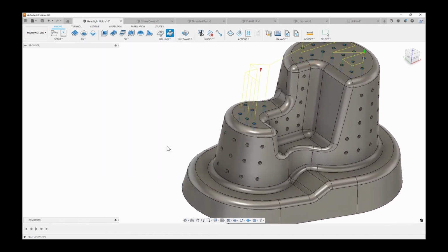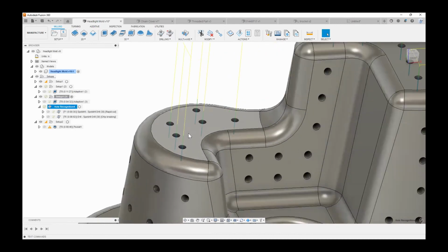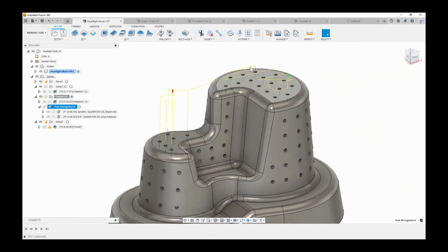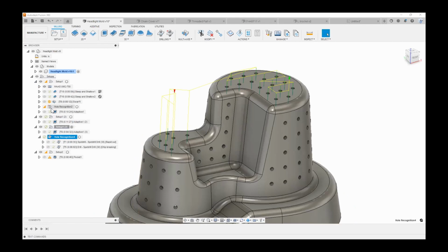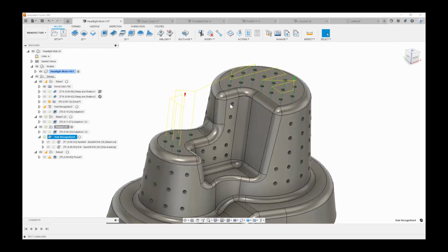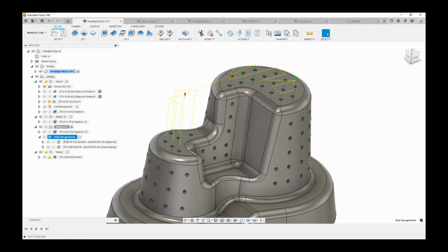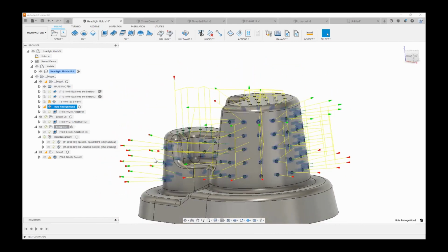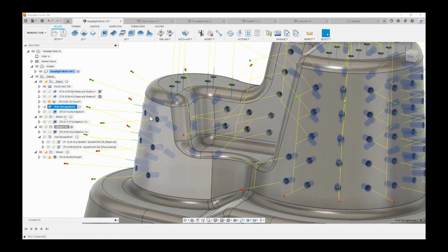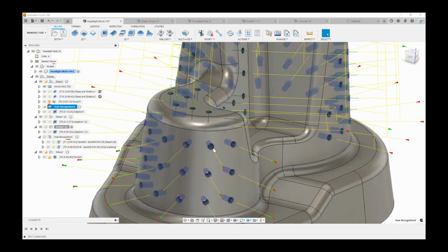I'm going to quickly just hit OK, just so you can see what that'll look like. And then as you can see, Fusion 360 automatically goes ahead and sets up my spot drilling and my drill holes. And again, you can edit this at any point in time as well. And you can set that up based on any sort of different tool libraries too. I have another hole recognition I made earlier. As you can see that now, instead of ignoring the side holes, we actually activate those.